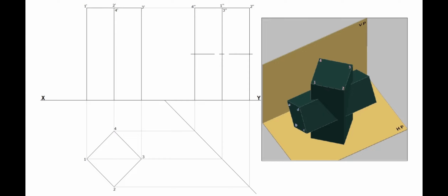Take the midpoint of it, and draw a 30 degrees line, and a 60 degrees line through this point. The side of the square is 25 millimeters. So, mark half of this, that is 12.5 millimeters, on both the sides of these lines. Draw parallel lines through these points. Now complete the square of the side view.